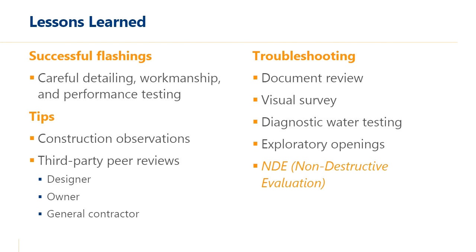For existing buildings, when troubleshooting issues that may be occurring or that you may be struggling with, we talked about several of the options here, but one thing we hadn't touched on was non-destructive evaluation tools in the toolkit to help identify some of these issues sooner rather than later. Whether that's thermal imaging or moisture imaging, each one of those is often project specific and may help troubleshoot an issue sooner than some of the other avenues, such as water testing and exploratory openings. So those are the main takeaways.